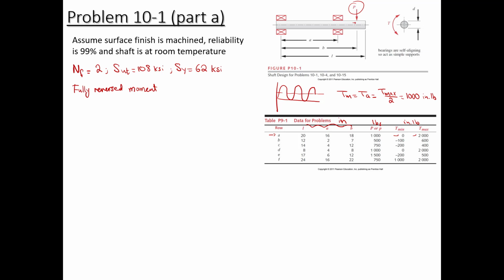For the moment, the two edges have 0, so the maximum moment will be at point, let's call this A, B, it would be at point B. So M at point B, if we look from the right side, we have MB, and we have the load P. If we take counterclockwise as my positive moment, I have minus MB, and then P is also rotating clockwise, so it's minus P times this distance, which is B minus A, equal to 0.